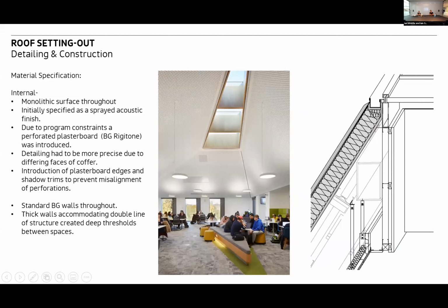Internally, the idea was we wanted a monolithic space throughout. Initially, that was intended to be a sprayed acoustic finish, but due to the programme constraints, because you have to almost block these coffers off every time we wanted to complete one, we decided to go down a rigid tone route. So this was a perforated board. The perforations were selected so that there were no linear perforations because of the changes in the coffer angles.